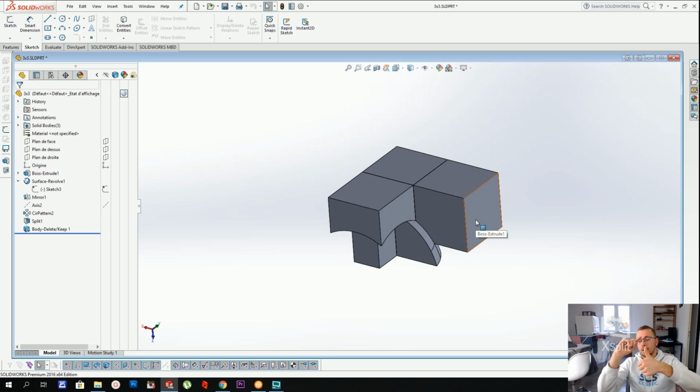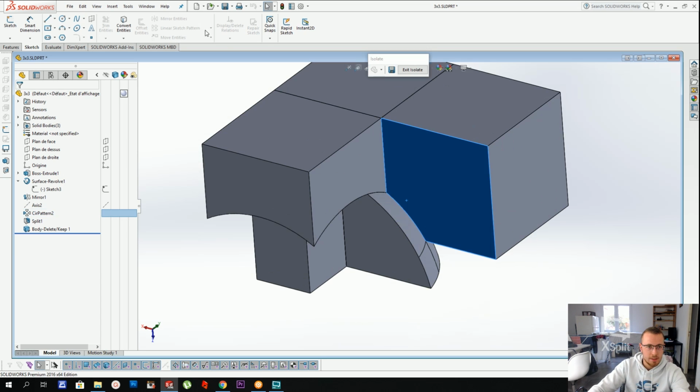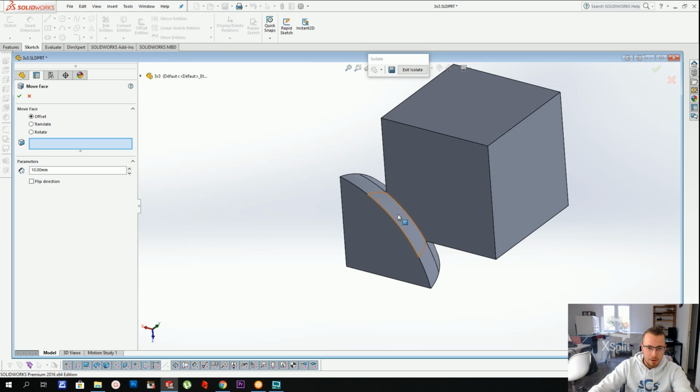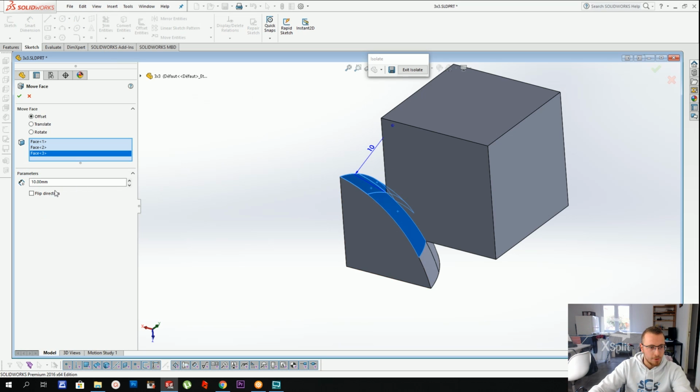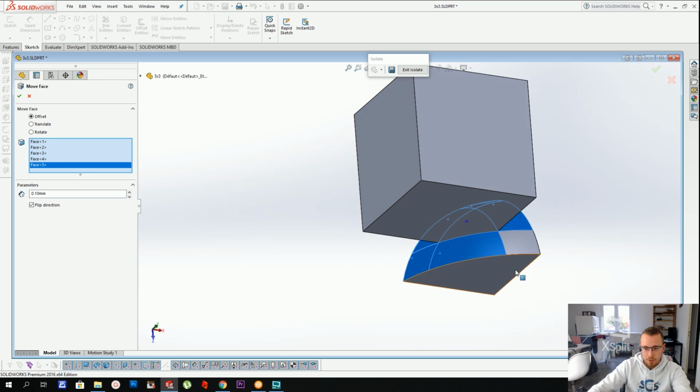So now, we're going to prepare the parts for 3D printing. That means creating tolerances, fillets, and screw holes and everything. So, luckily for us, there are no tolerances to be put on an SLS printed puzzle. Sorry, on an FDM printed puzzle, you would need to put tolerances because FDM isn't as precise. So you'd need to add tolerances on the whole part. I'm not familiar enough to give you advice with certainty, but I guess around 0.1 millimeters removed on all faces.